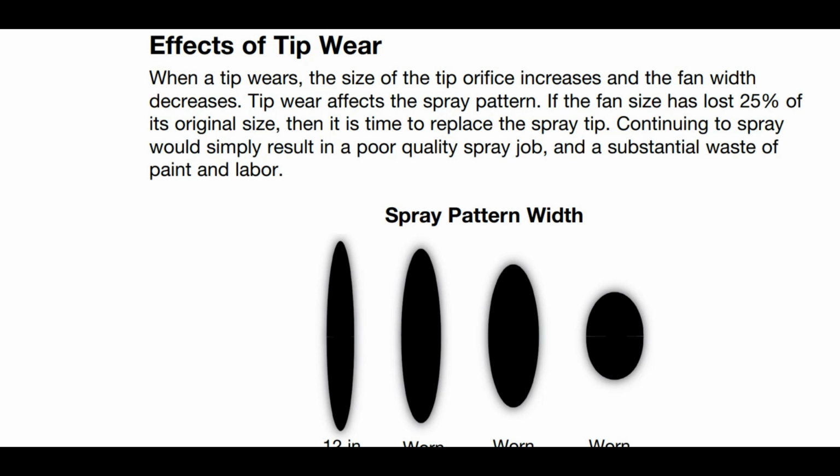The effect of tip wear. When a tip wears, the size of the tip orifice increases and the fan width decreases. Tip wear affects the spray pattern. If the fan size has lost 25% of its original size, then it's time to replace the spray tip. Continuing to spray would simply result in a poor quality spray job and substantial waste of paint and labor.